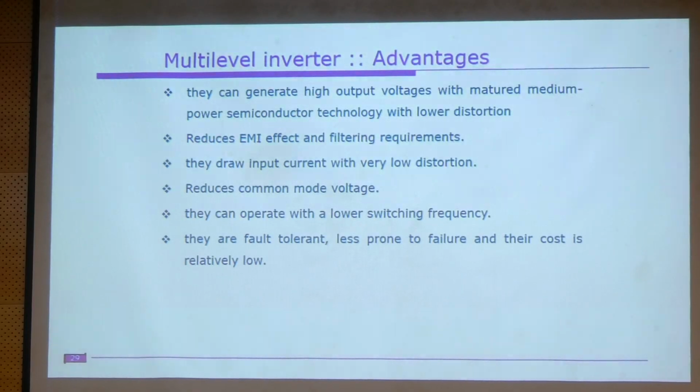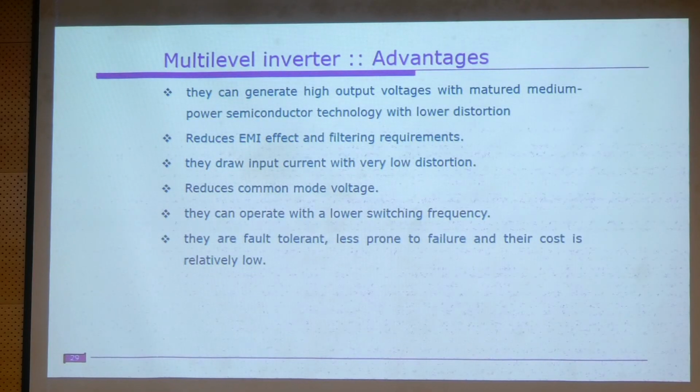So when you are feeding these waveforms, like this waveform which contains the common mode voltage, this common mode voltage is of high frequency, right? If you apply a capacitance to a high frequency, how will it act? You know that, right? It is 1 by XC, so the capacitive reactance is in the denominator, which means the impedance will be very small. So it will allow more current to flow through the capacitor. Understood? It will allow more current flow through the capacitor.